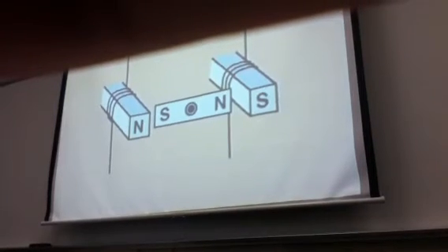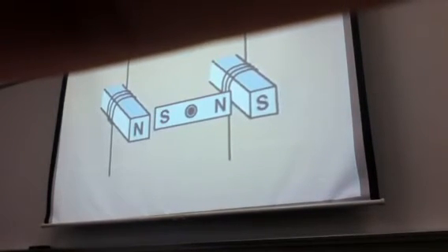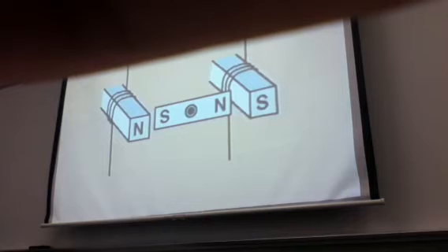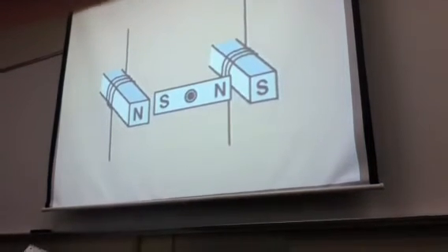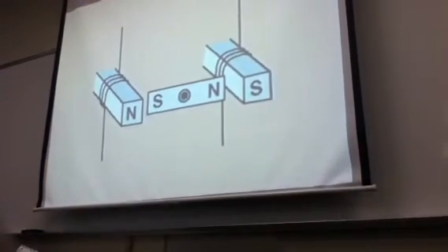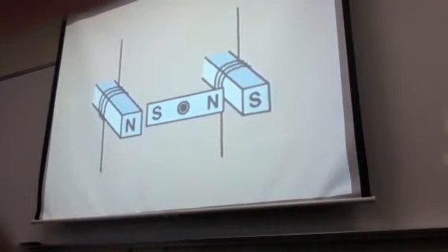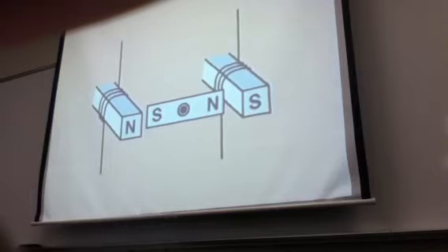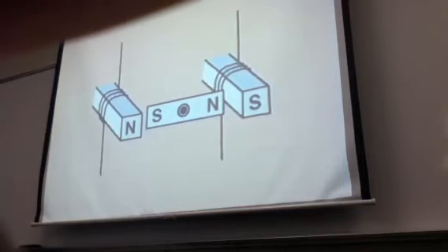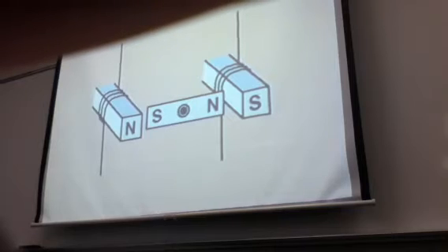It seems to work well, but let's look closer. If the magnetic rotor stopped in the position shown, we could not restart the motor regardless of the polarity of the two stator poles. Here, the rotor and stator poles attract, and no motion occurs. Even when the stator poles reverse, the repelling forces will be at such an angle that the rotor will not turn.